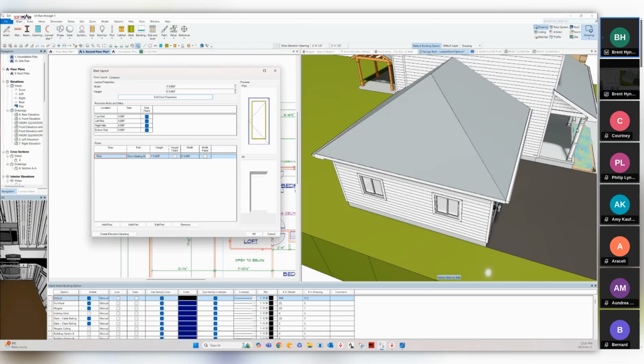So just to get to what the real purpose of the door layout tool is, you may hear the term parametrics thrown out there. The fact that we can do this in this tool and make a parametric opening means that I can take this particular opening, whether it's 3 feet or 10 feet wide, and have certain items scale up while certain items on there, such as the rails and stiles, will maintain their original size and not stretch with the size change. Okay.